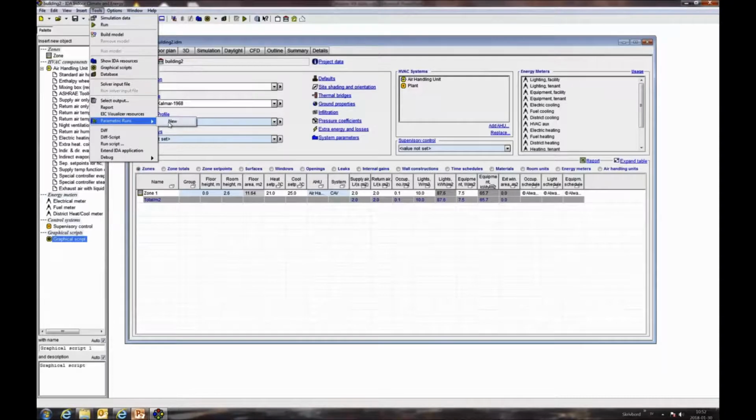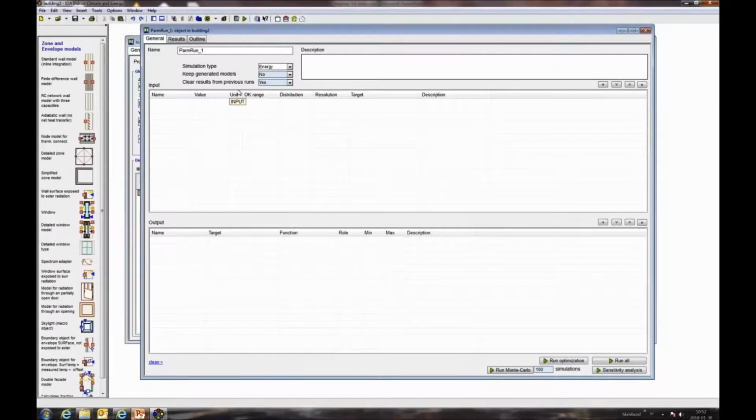Maybe I can answer that question. Yes, you will be able to. Basically, IDA needs to have a single scalar result to be able to optimize with respect to. So if you have a curve of things happening, like a temperature variation, then you have to build an advanced level, log that signal, and snap to the maximum or minimum, whatever part of that curve you want. Then that variable that holds the snapping, you can add to the parametric script. And that question was answered by our CEO, Per Salin.